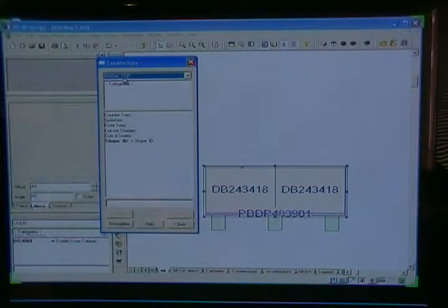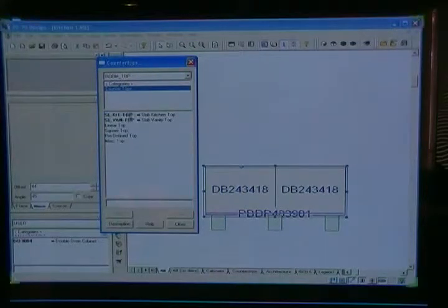As you see here, now we got room top, so I have an option for countertop, splashes, front trim, but the option countertop will only come up when you're creating 2D line work that is closed up. Either it's a circle, or a rectangle, or an irregular shape like a star, as long as every line joins together and it's considered an enclosure.